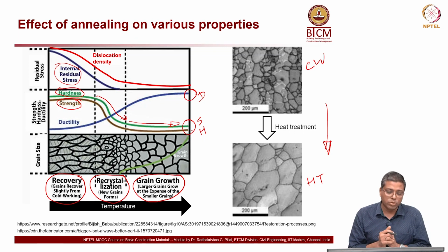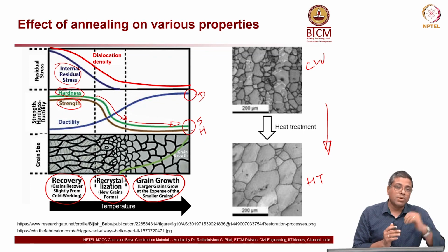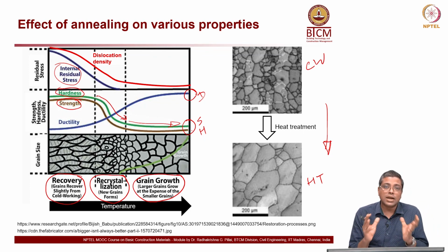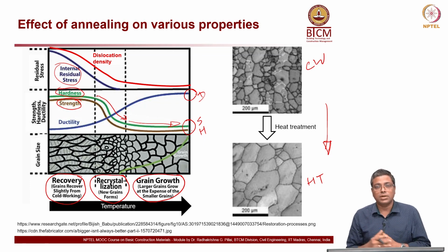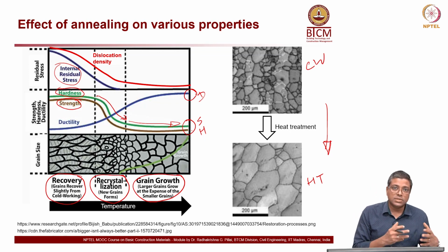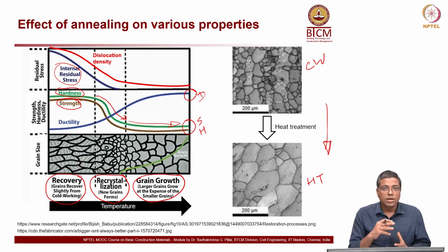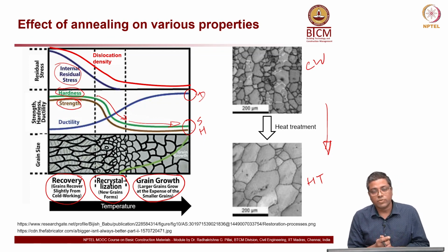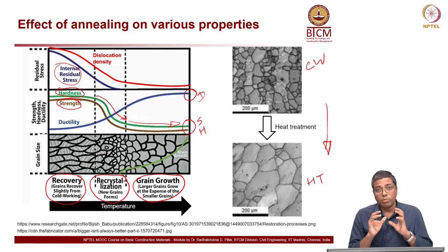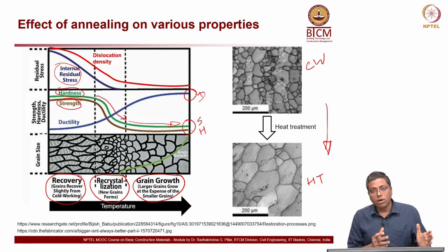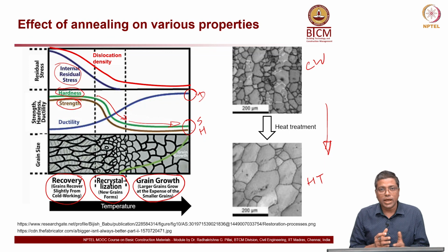Hardness, how much it should be, ductility, how much it should be, strength, minimum how much it should be. All those target values for these properties will be given at the time of design, and then the steel manufacturer has to adjust the composition of the material, I mean the raw materials put in the molten material, and the manufacturing process, or the cooling rate, or how many times you do these heating and cooling treatments.